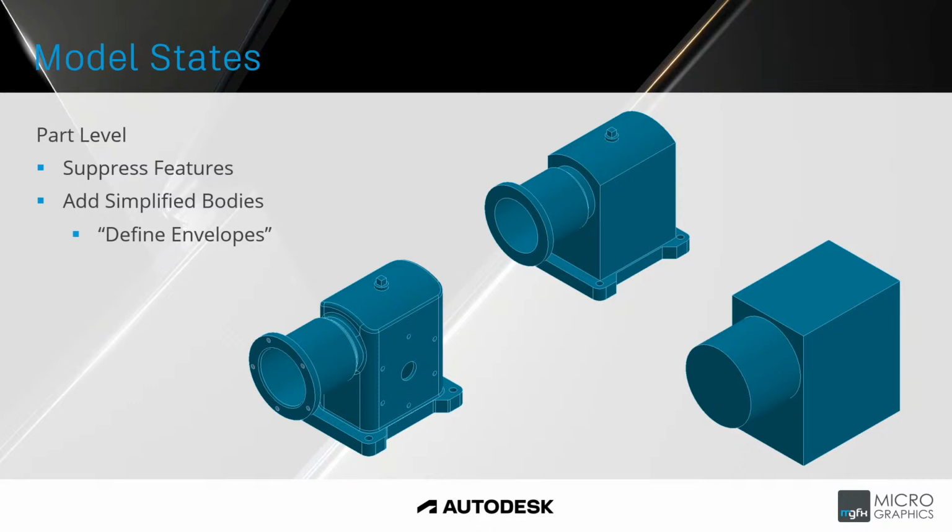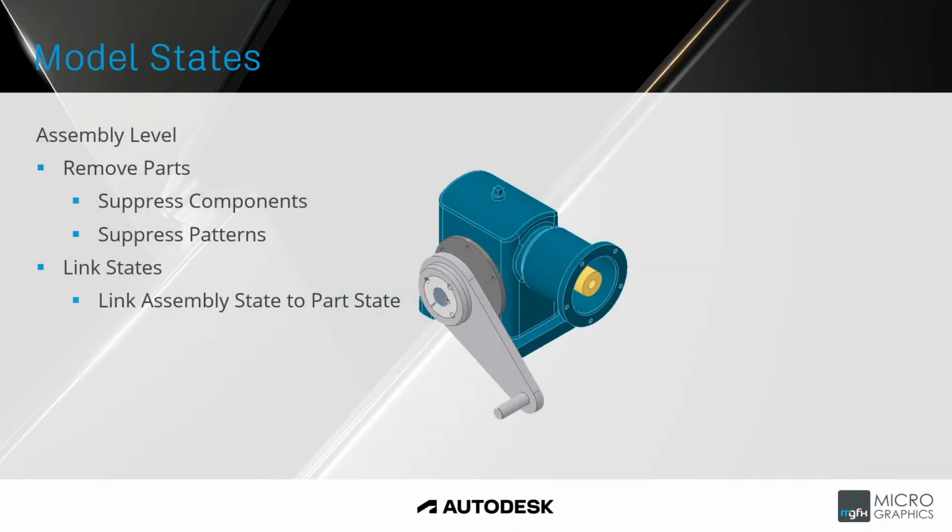We will be going through a demo of these features as well. We will just have a look at the assembly level model states, and then I think we will be moving into a demo covering Express mode and states. But if we have a look here now on the next slide, we can also work with assembly level model states. At assembly level, we can use the model states to remove components, either by suppressing the actual component itself or suppressing patterns that generate multiple components.